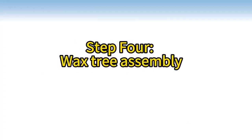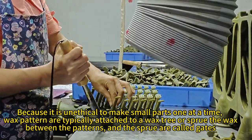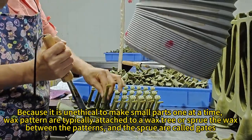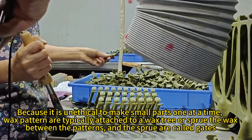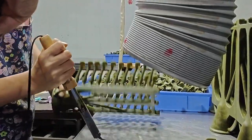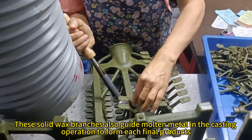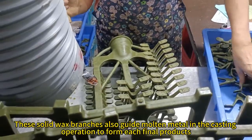Step 4. Wax tree assembly. Because it is uneconomical to make small parts one at a time, wax patterns are typically attached to a wax tree or sprue, the wax between the patterns, and the sprues are called gates. These solid wax branches also guide molten metals in the casting operation to form each final product.